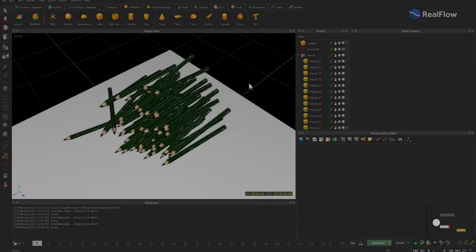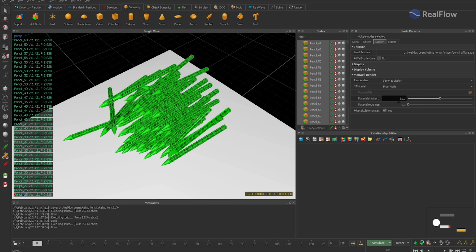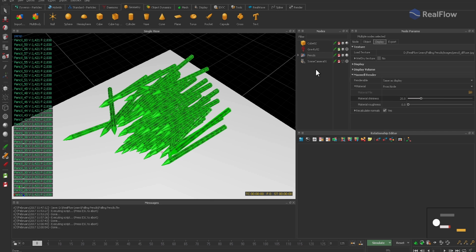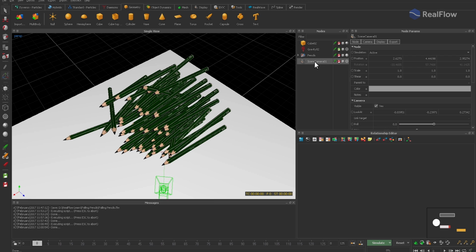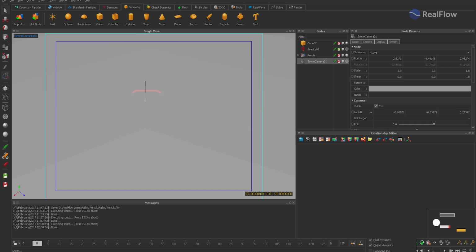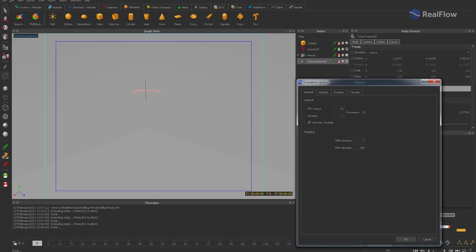For the final render, it's also possible to change some basic material properties like reflectivity. And here I also want to activate a predefined perspective by dragging a camera to the viewport. Before we simulate, we open the project simulation options next to the Simulate button. And since we have a pure rigid body simulation, all substeps can be set to 1 and 25 is enough for the rigid body solver's quality. These two simple changes will make the simulation roughly 5 times faster and finally set jittering to 25 to keep a slight amount of motion.